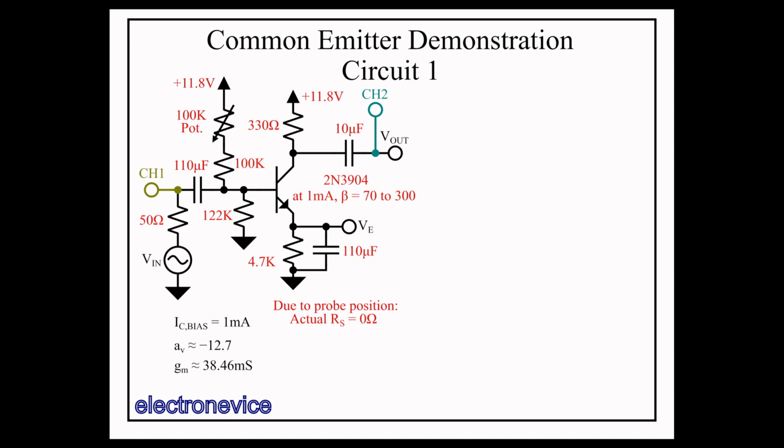I also want to point out that in order to demonstrate this circuit well, we have to use very low voltages and measure those voltages. Oscilloscopes in general don't do well with sub 10 millivolt signals. In particular, 10x probes introduce a lot of thermal noise into the system, as well as incorporating a factor of 10 reduction in the signal. Fortunately, 10x probes only become necessary at relatively high frequencies. So long as we keep our frequencies low enough, we should be okay to get rid of the 10x probe.